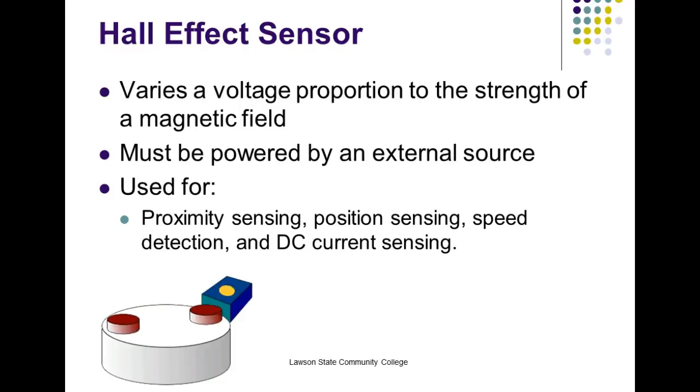So what we're showing down here in this little animated GIF is some magnets spinning around. And can you see what it's doing? Every time the magnet spins around, it pulses. By the way, these are all in your car. We use these to pick up for usually your ABS system, your automatic brake system. So on your rotor, it's got a magnet, and a little Hall effect sensor sensing the speed of your actual rotors.